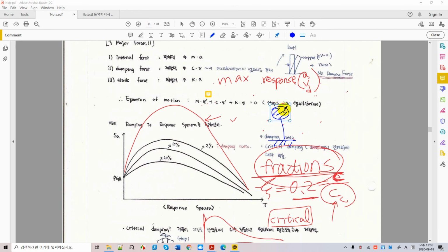So the top of your mass has only one freedom to move, in which direction? Yes, horizontal direction. Your building can only move in the horizontal direction. It is called a single degree of freedom system. It's easy, isn't it? So your definition of your response spectra is for a one-story building, which is one single degree of freedom system. Okay, now understand the definition of your response spectra.